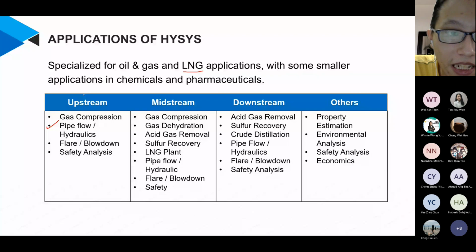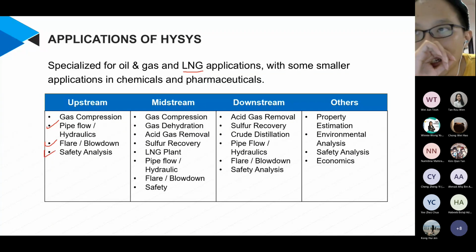You can also have a flare analysis, where if you want to build a flare, you can calculate how big the flare is required and so on. You can also do safety analysis like pressure relief valves. You want to know what kind of pressure relief valve is required, how big it is, and so on.